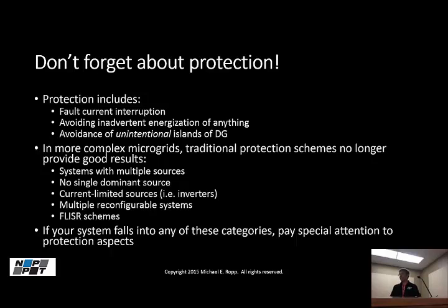What happens in a case like that is you don't have enough fault current that you can blow fuses or that you can reliably use overcurrent protection to sufficiently protect the system. Sometimes you can, because some battery inverter systems will have a function in them so that they source a lot of fault current. You've got to be careful. The inverter has to be sized for it, right?